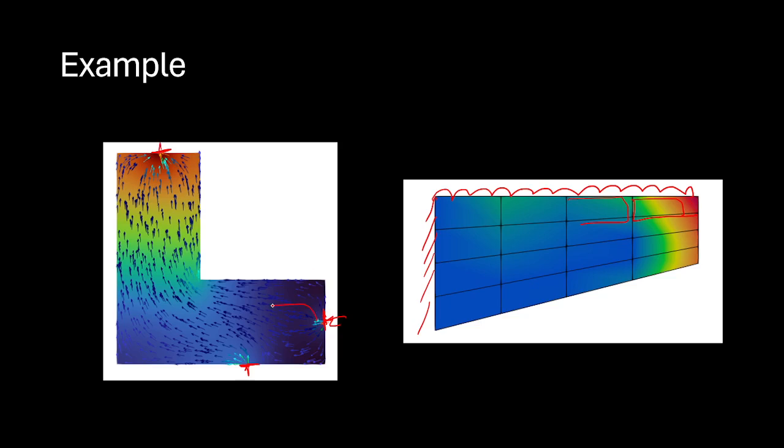This arrow shows how current is passing in this bus bar, and the blue and solid contour lines provide the temperature, where the temperature is high near the port and the ground port, because all the currents are coming here. A high current implies I squared R, which increases heat, and higher heat means higher temperature.